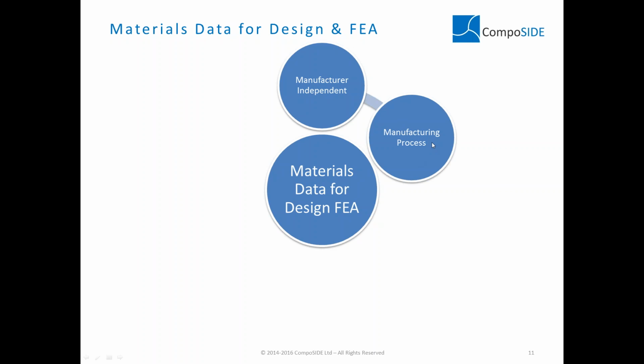To each one of those, I mentioned we have associated a manufacturing process. So whether you're looking at hand layup, vacuum infusion, or automation, there are certain characteristic values that change according to the material and the process selected. And basically this data is able to support an initial material selection when you start designing or evaluating the options and properties of a number of composite parts.